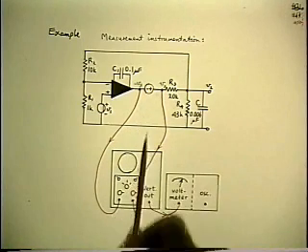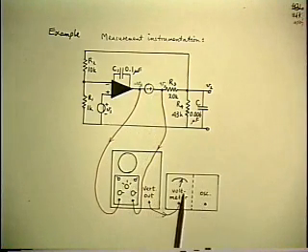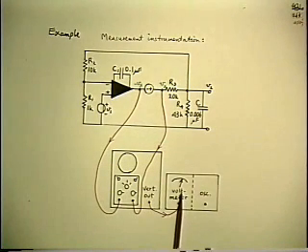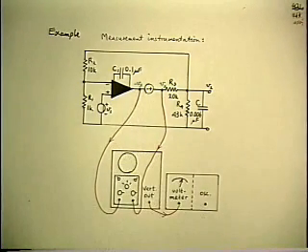Which means by measuring differentially, you get a third reading on the meter, which is a magnitude also, but it's the magnitude of the third phasor. So what you do actually is measure the 3 sides of a phasor triangle. And then you dig back into your memories of old high school trigonometry, and you remember there is a formula that says if you know the three sides of a triangle, you can calculate the angles, known as the cosine formula. Maybe you've forgotten it, but anyway, you remember that it exists. And so that's what you can do in this case.